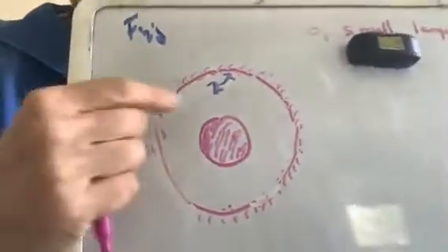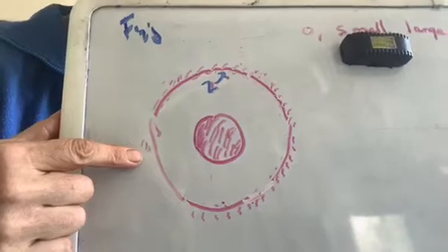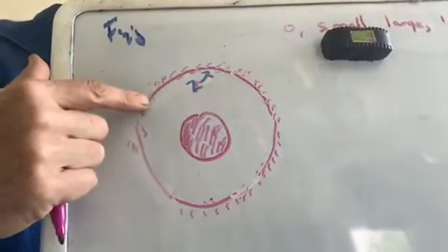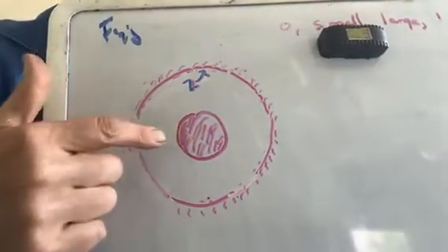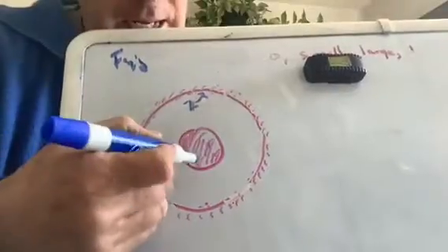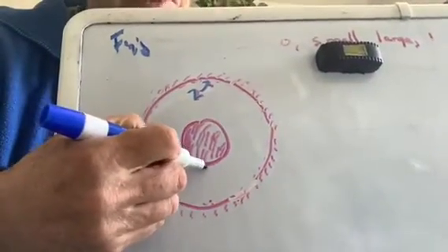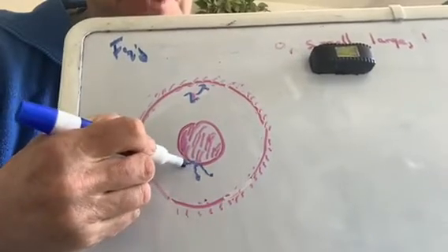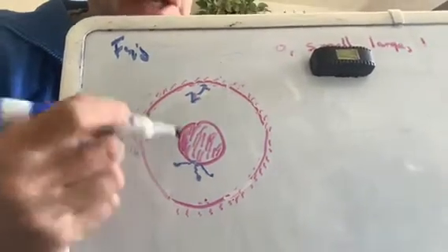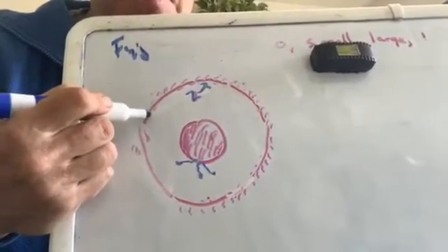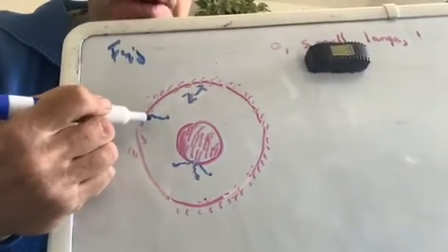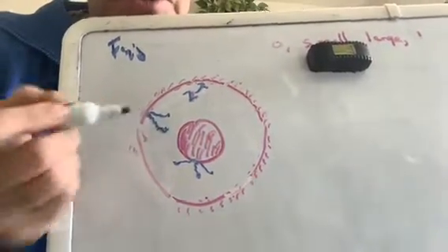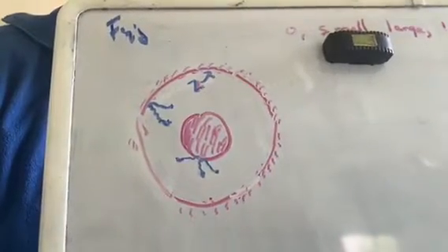let's imagine that we have a sphere within a sphere and just do that classic problem where we figure out the radiation view factors. So 2 is going to be the outer hollow sphere, and then 1 is going to be this inner sphere. And both are radiating. So I'm going to say, just this point right here, both are radiating diffusely. 1 is radiating in all directions at every single point on that sphere. Same thing with 2. If I go to every single point on the inner surface of the sphere, it is radiating in all directions, okay?